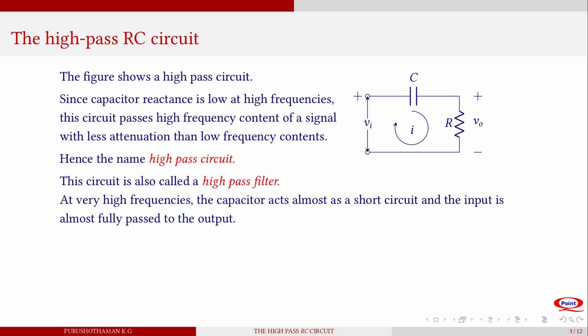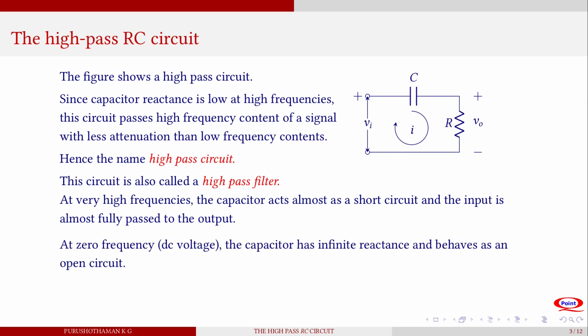At extremely high frequencies, the capacitor acts almost as a short circuit and the input is almost fully passed to the output. At zero frequency, that is at DC, the capacitor has infinite reactance and behaves as an open circuit. We say that the capacitor blocks DC.